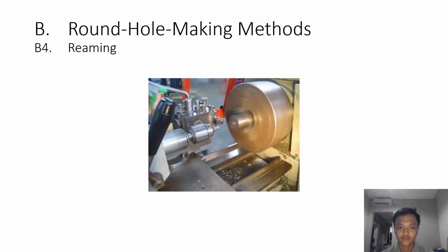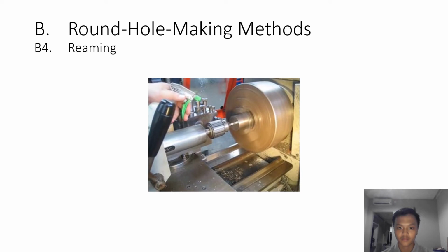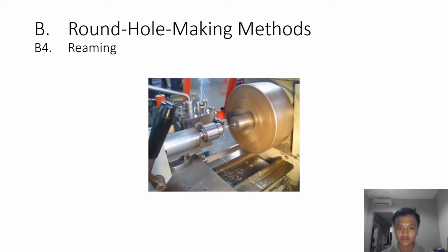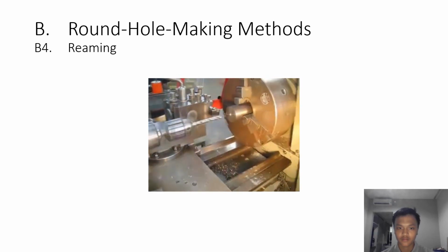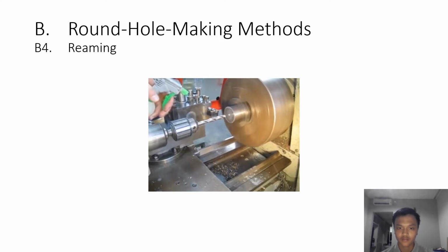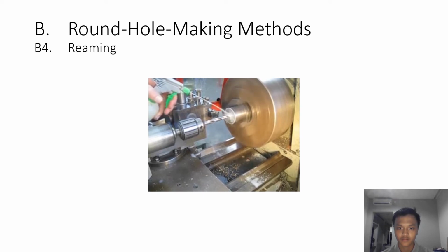Maintain a high speed for center drilling. Remember to use coolant on high-speed steel tooling, such as this center drill. Note that the center drill should be drilled to a depth of at least 2/3 of the chamfered length. Calculate and set the drilling speed according to the drill size. In this case, an 11.5mm drill is used at approximately 800 RPM. Once again, coolant is used on this high-speed steel drill bit.